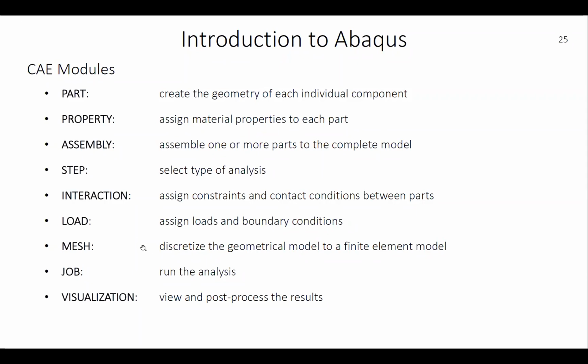But when you come to the mesh module, here is the important part for discretizing your geometrical model into a finite element model, and also defining different element types, the order of elements and the type of elements.